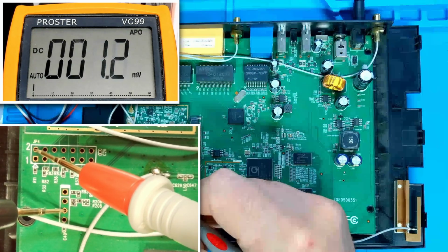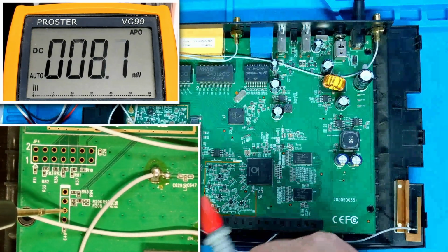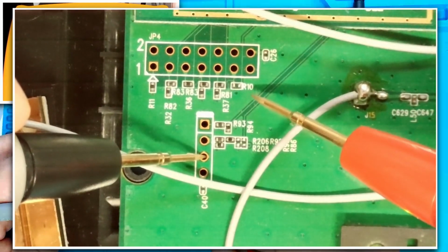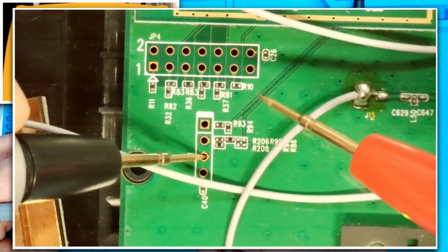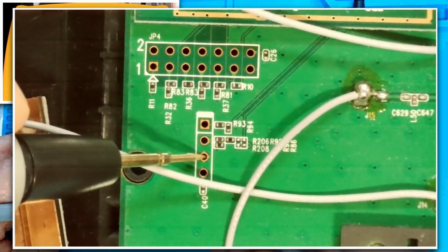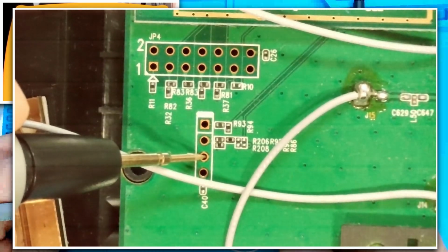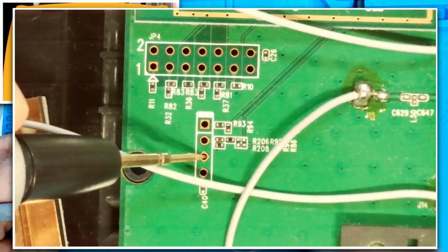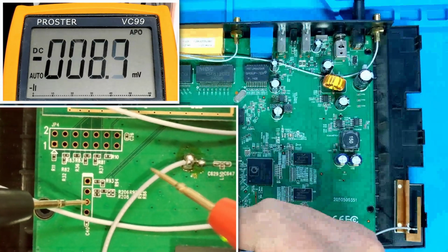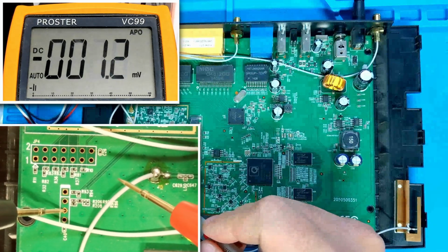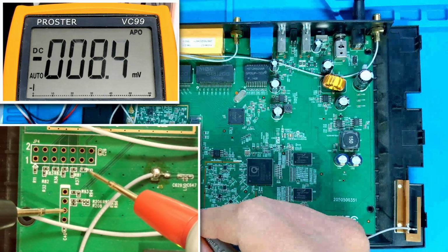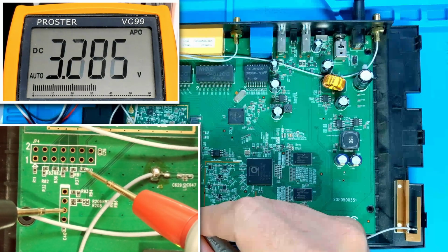So we don't see anything on here that is 3.3. But something interesting that we do see is this R10 resistor right here, which is not populated. And sometimes unpopulated components can kind of point to an interesting signals. So it's something that maybe they needed that circuit in development or testing, but they don't care if it's there in production, which is definitely something that you would find with like a reset or a programming interface. So let's go ahead and look at the other side of R10. And we can see that that is 3.3 volts.